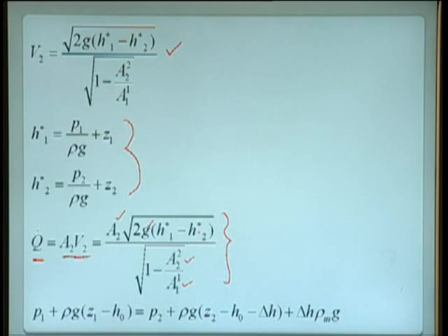Now, if we are using the U-tube differential manometer, then with the help of this formula, which we have studied when we discussed about the manometers, we can find out P1 over rho g plus Z1 with the help of this equation. Let me write this equation again.